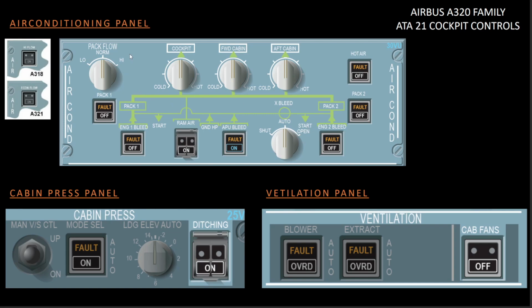Okay, first of all we have the backflow selector here. You can see that it has three positions: low, normal and high. You can place the flow selector in any of these positions. If you place it in low position, you will get a flow corresponding to 80% of the supply. In normal position, you will get 100% of flow, and in high, you get 120% of flow.